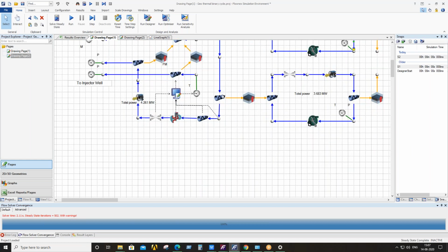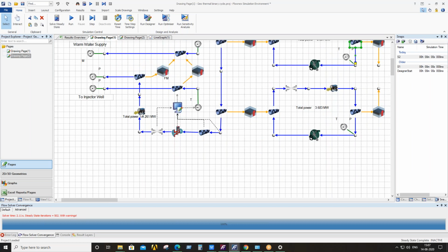So here it again exchanges heat with the second Hexane cycle, and again the steam quality reduces to 0.627 and the temperature also reduces. Since we are supposed to connect one steam turbine in front of this line, and it is already in the saturated stage of steam, we have to remove those liquid particles from the steam. So that's why we use this steam trapper. It separates the liquid phase from the steam phase, and only steam is allowed.